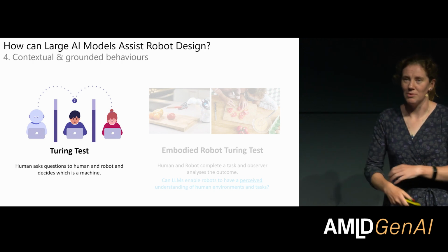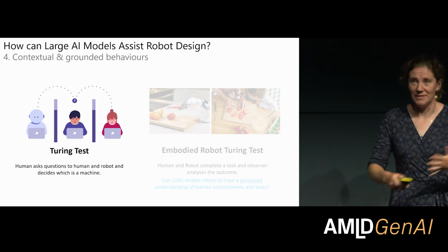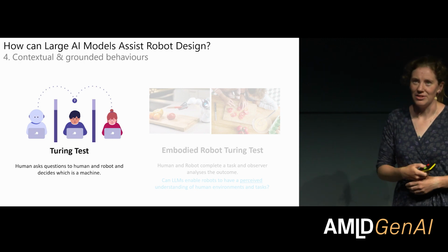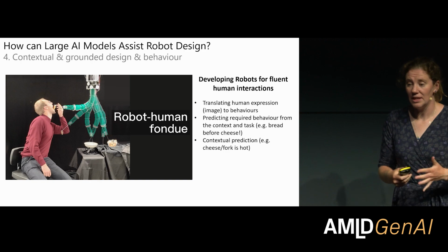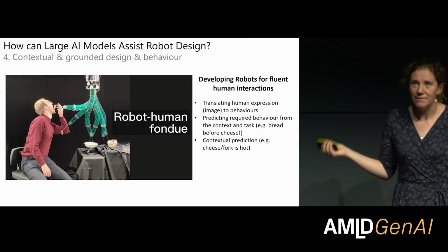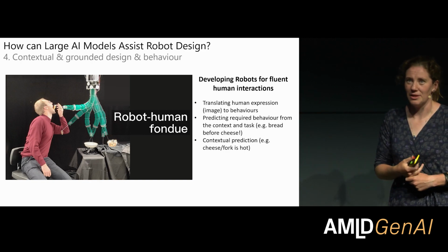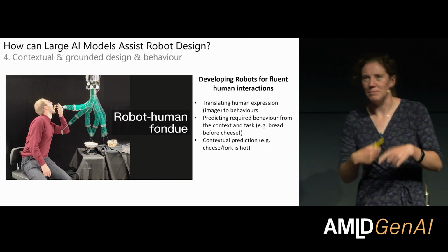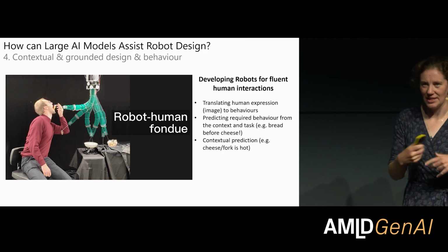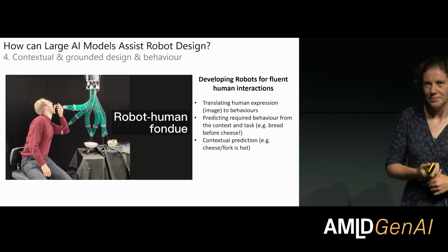STL to G-code is a little bit more challenging because you've got a myriad of settings in how you do your slicing. But for the kind of designs and structures we were looking at, that was a fairly seamless process. Going more complex than that, there are going to be similar limitations. So there's a need to have an additional sanity check in the loop there.